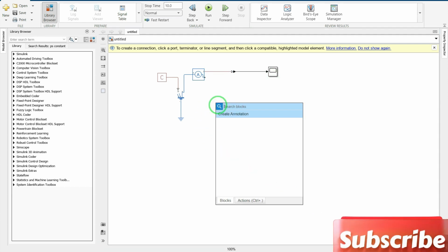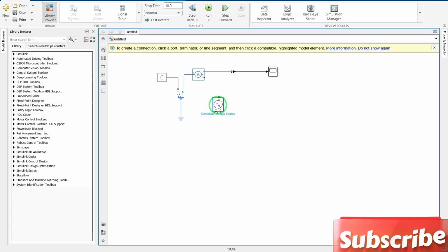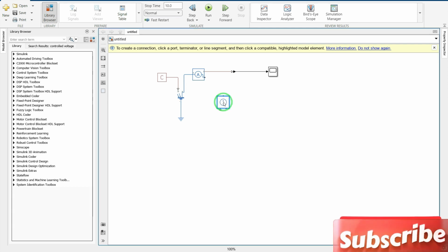And then we have our controlled voltage source, the second one here, not this one. While choosing the controlled voltage source, be careful to choose it from the Foundation library, the blue line libraries, to be able to connect the components to each other.